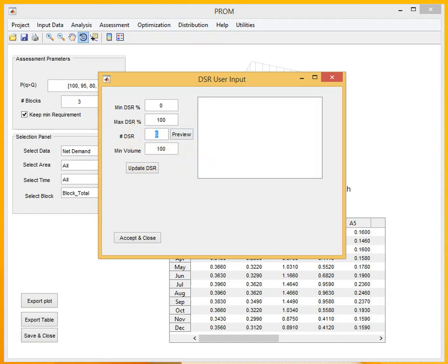For the Mara River Basin, we used 4 intervals, and the minimum volume is useful to avoid division by 0. Let's put 0.001. Whenever the flow volume is really low, that value would be assigned. So the first is from 0 to 10.